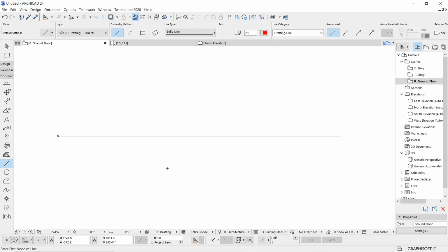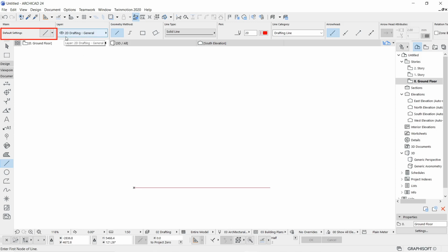So once you have completed this single line segment data entry with the help of the coordinate method, let's try to complete this room rectangle by adding the remaining three segments. And this time we'll try to improve our data entry step by step. Say for example, if I want to start, make sure again that in your default setting the line tool is already available. That is, your info box shows that the line tool is loaded with the default setting as a wall.